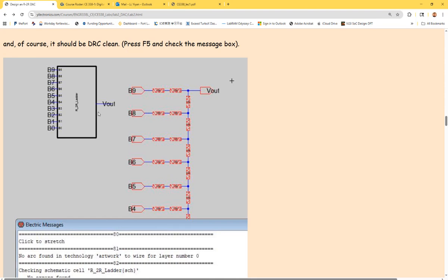You basically, when you are designing circuits in VLSI, you don't worry about the internal structure because they're already in there in the sub module. So what you care about is just the ports. Okay, just inputs, outputs. So you create an icon from it, and you are only using the inputs and outputs from it. So just create an icon and put the ports, make the ports available.